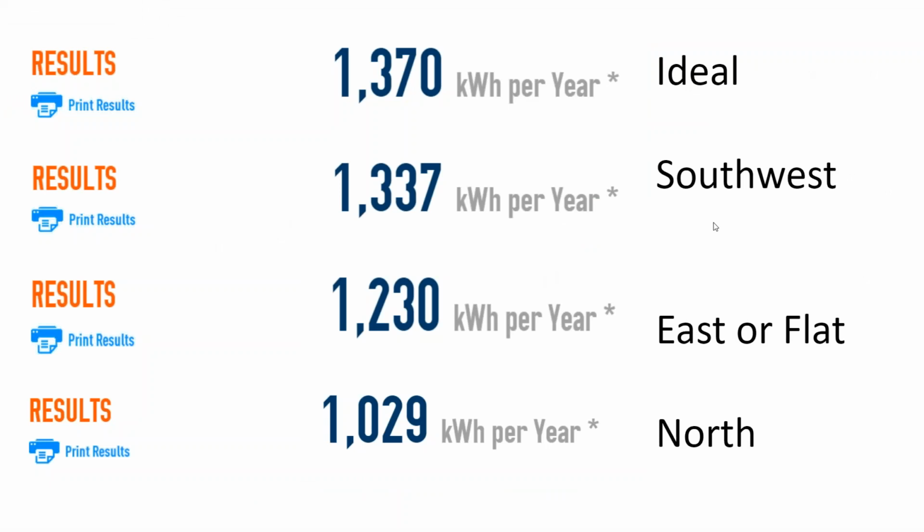So when I approach a rooftop, I'm not too concerned about what the ideal roof is. I'm looking for large open roof surfaces that preferably have a southern orientation of some degree, but if the surfaces are large enough, I'll do east and west. And if the roof is a shallow enough tilt, then there are cases where I would consider the north side of the roof if the client still had budget and still had an electric bill.